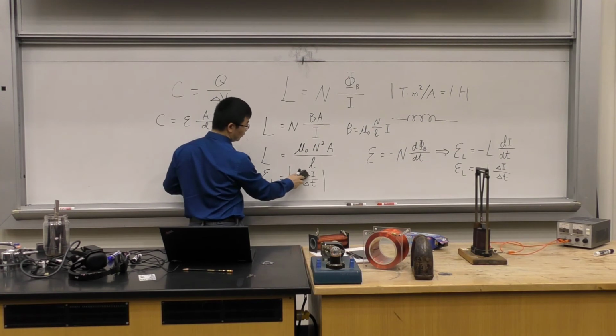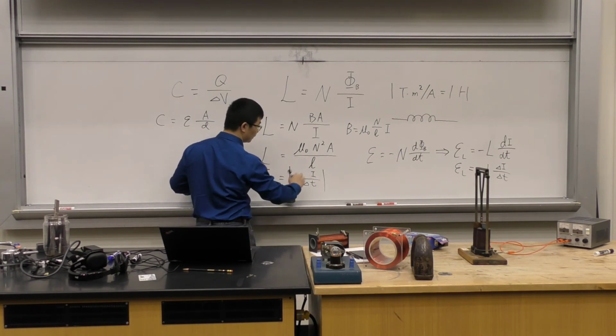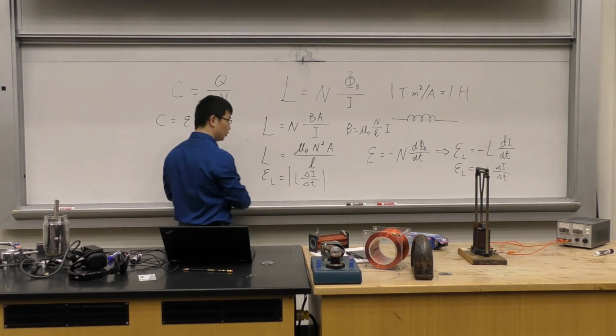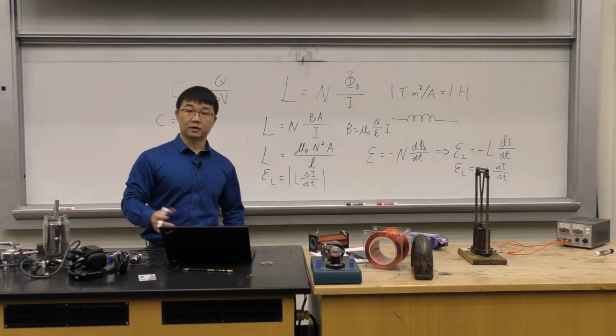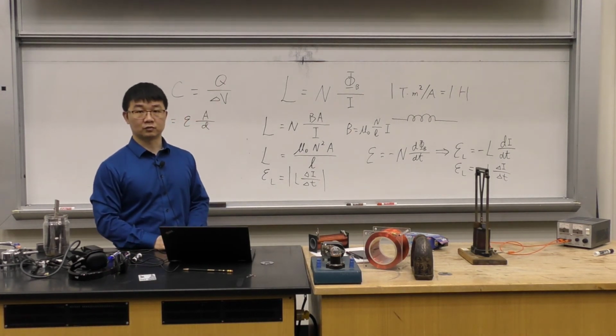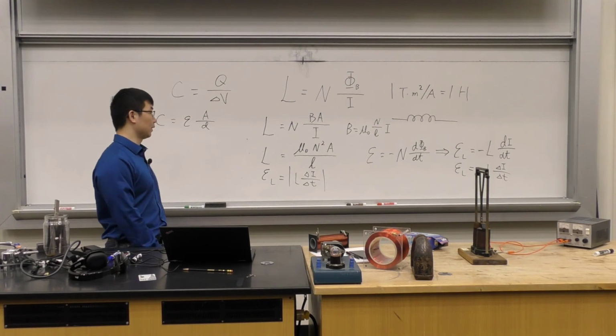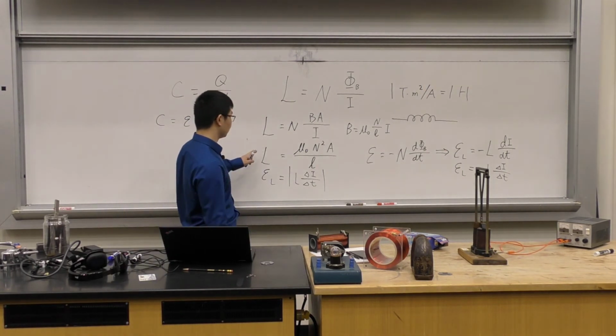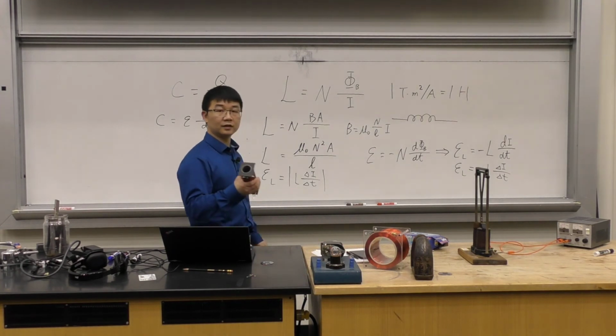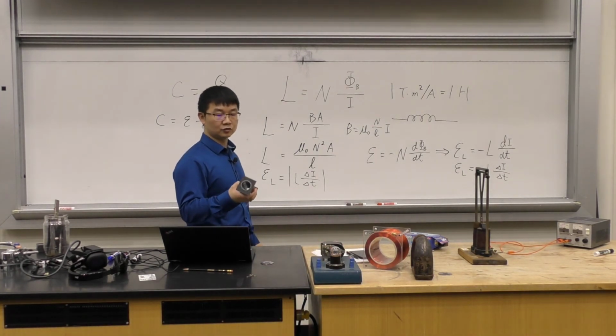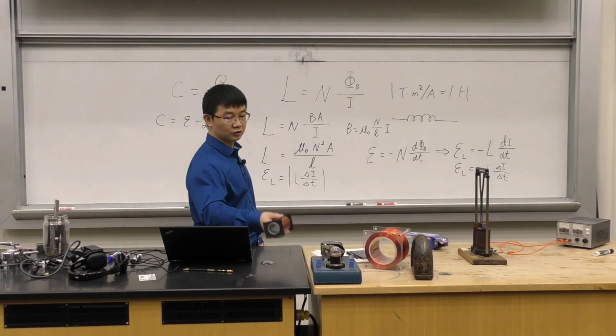And now, if you want me to find the direction of the induced voltage or current, I'm going to use Lenz's law. I'm just going to do the 4 steps. Okay? So that's the reason we want to define inductance for a solenoid. So calculating the EMF, induced voltage is going to be much easier.